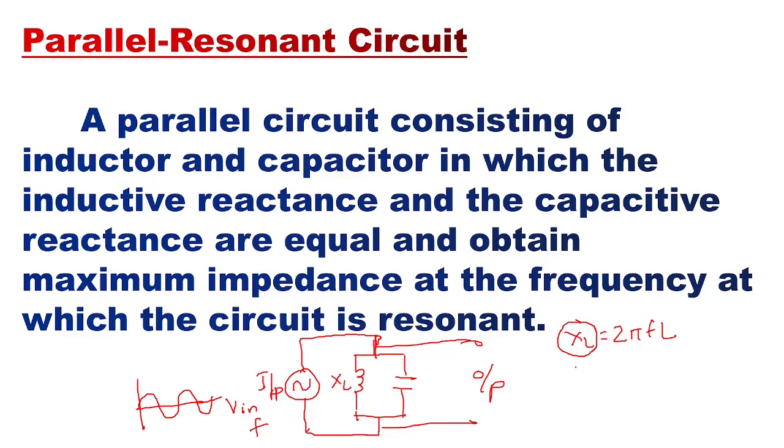Similarly, the reactance of a capacitance, Xc, is equal to 1 by 2 pi Fc. This reactance is inverse to the frequency of the input. If the frequency of the input increases, this reactance decreases. So there is an inverse relationship between the reactances of inductor and capacitor.